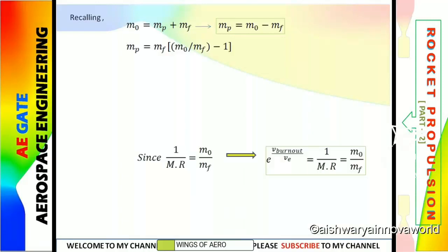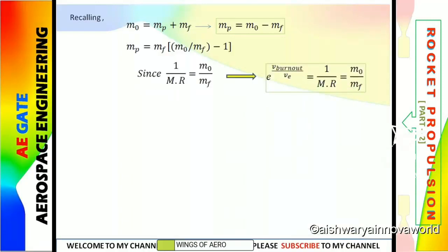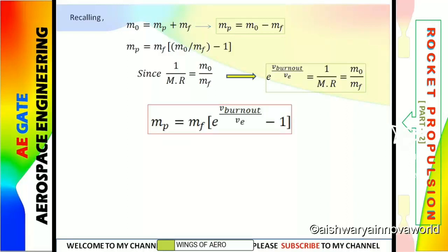From there, recalling the value again, that is exponential of v burnout by v effective, we get 1 by the reciprocal of m dot r. This is the mass ratio. So substitute the value over here. You better remember this equation, because they might ask this kind of question for 2 marks. You better remember this procedure. It is better than memorizing this formula.